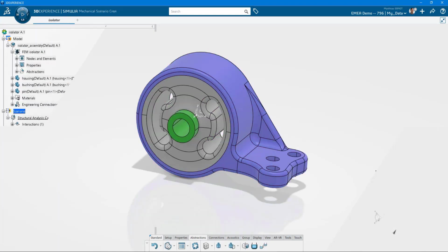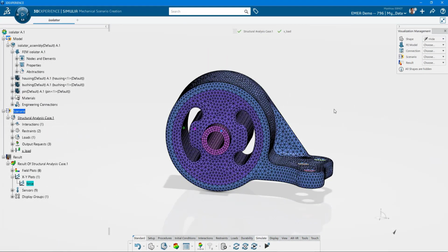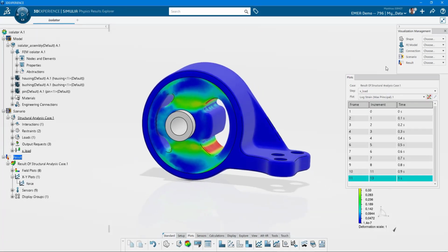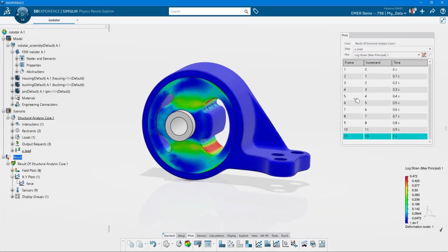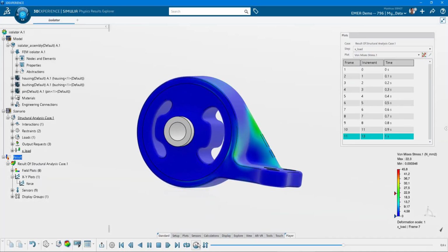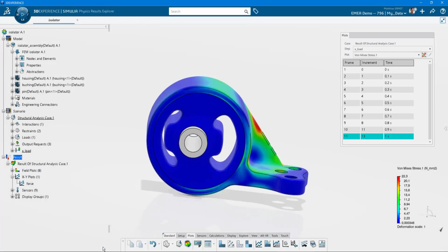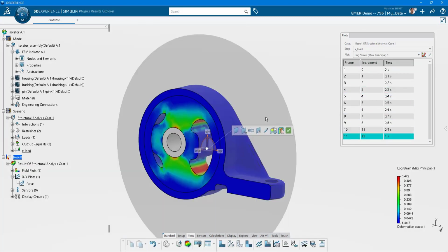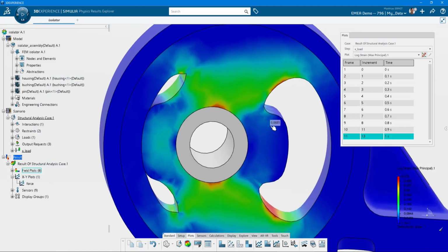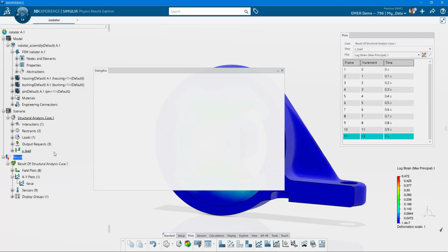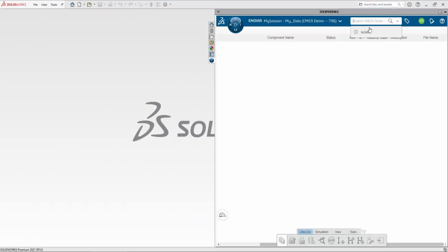We make a cut to save time, and we go directly to the created simulation and to the results we've achieved. We'll just have a look at the basic post-processing capabilities. Of course, there's much more possible, but we just had a brief look at the mesostress, doing an animation, switching the result variable, for example, to a strain, using a cut plane to look inside, and also using an XY plot to have a look at the force displacement graph.